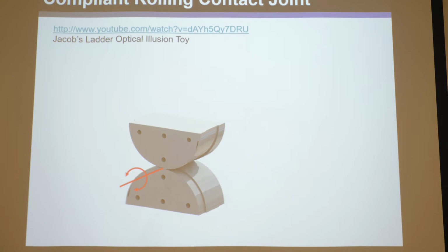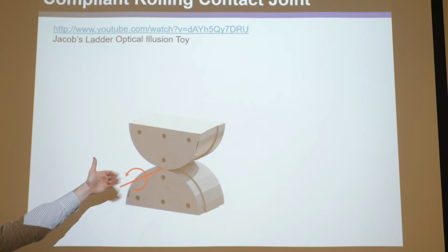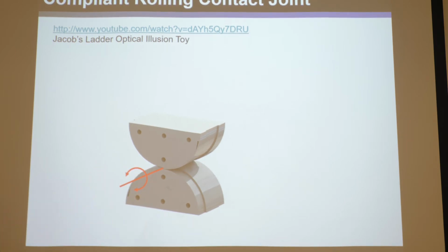So these are used all over in compliant robot joints and all sorts of things. So always consider using these. And they enforce rolling contact motion. So they're basically like compliant gears, except instead of all the rubbing and friction in the gears and all the issues that come with rigid gears, it's largely sidestepped. The one downside is gears can keep rotating forever, and these have a finite range.